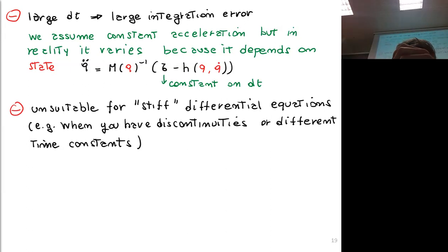However, as I said, our manipulator in free motion is not a stiff dynamical system, so we can use explicit Euler with quite a small time step from 1 to 5 milliseconds. While in the case of an electrical motor, it wouldn't work, and it would be unstable and inaccurate.